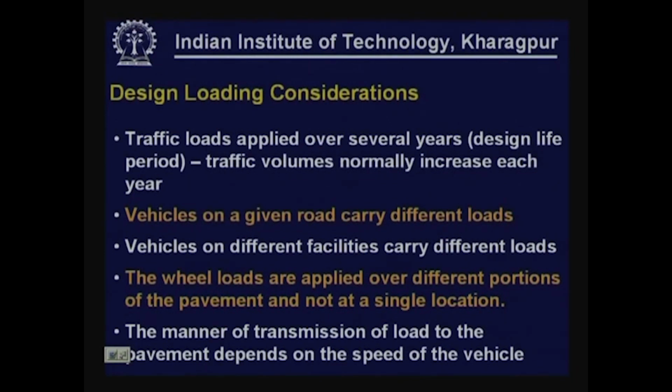Among the design considerations that we have to have for selecting design loading, we have to appreciate that traffic loads are applied over several years. These several years could be design life 10 years, 15 years that we select, and traffic volumes normally increase each year in most cases.